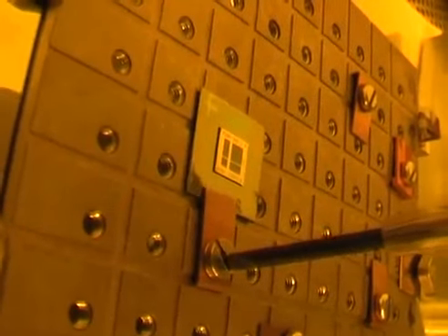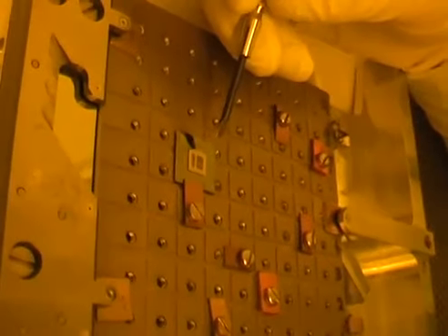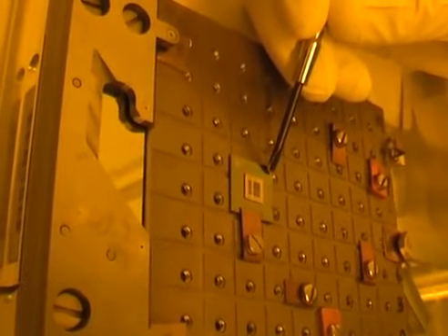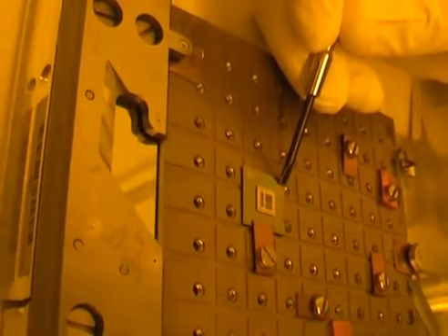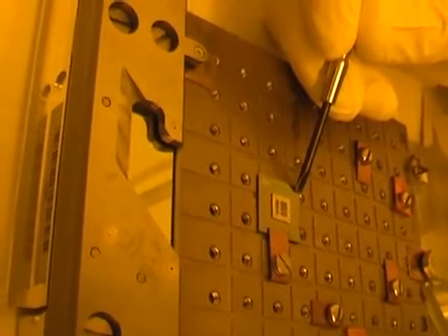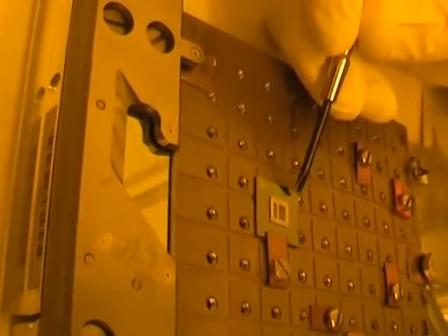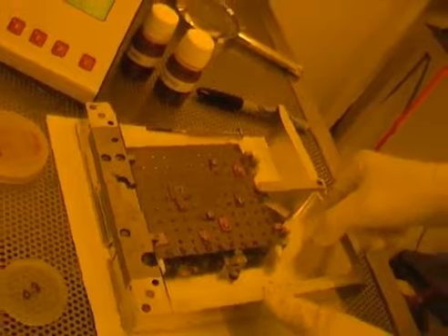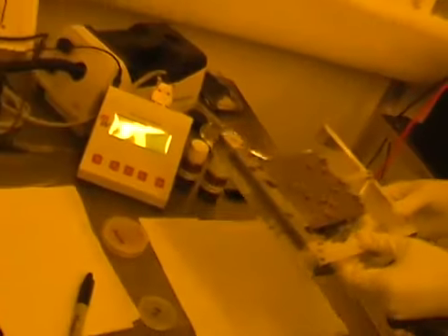And then clamp it there. What I usually do is I then just push the sample here, and if it moves at all, you can usually see it quite clearly. In fact, I can see that's moving. But I think it's not moving too much. Judgment call. What I'd now do is I put it into the alignment microscope, and there I can actually measure the flatness and I can measure the rotation.